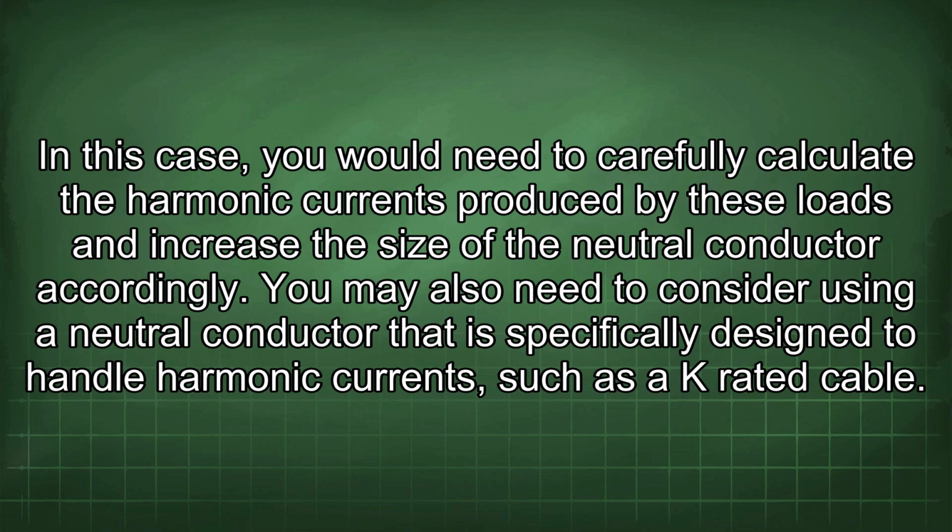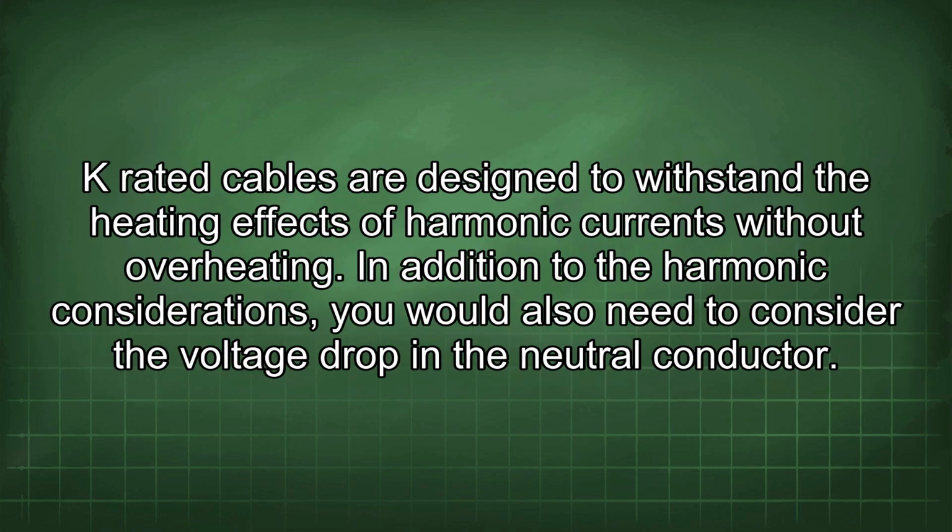You may also need to consider using a neutral conductor that is specifically designed to handle harmonic currents, such as a K-rated cable. K-rated cables are designed to withstand the heating effects of harmonic currents without overheating.